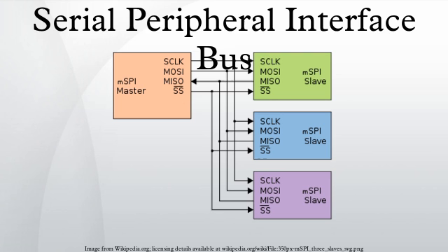The chip select line must be activated, which normally means being toggled low, for the peripheral before the start of the transfer, and then deactivated afterwards. Most peripherals allow or require several transfers while the select line is low. This routine might be called several times before deselecting the chip.